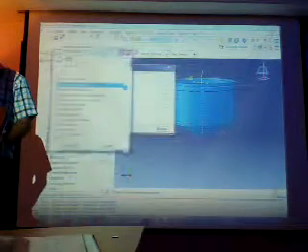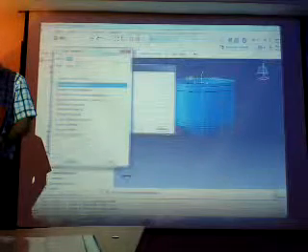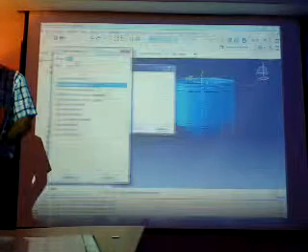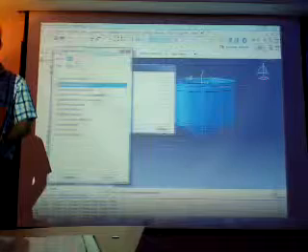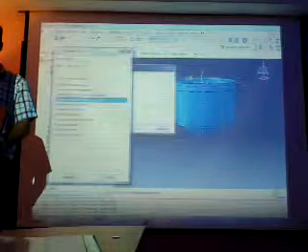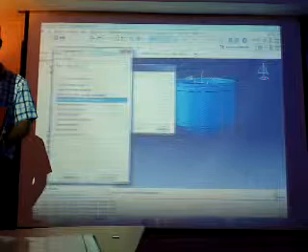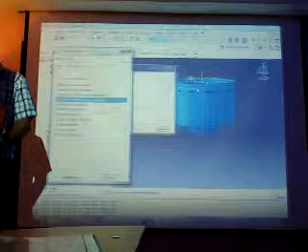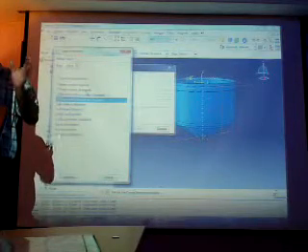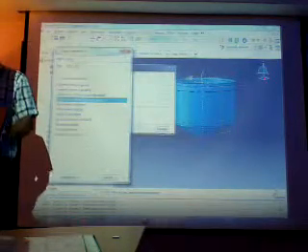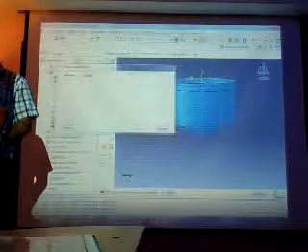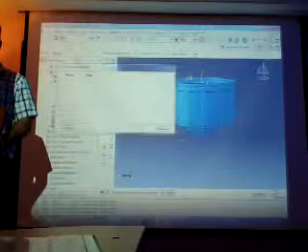Create. Here you can see different kinds of interactions. As we are going to select an explicit step, it is important to take explicit one or general contact. General contact is not accurate enough for a process like extrusion. If you have, for example, two parts and you have bending, that's okay. But for this one, surface to surface contact is very important to take. So continue.